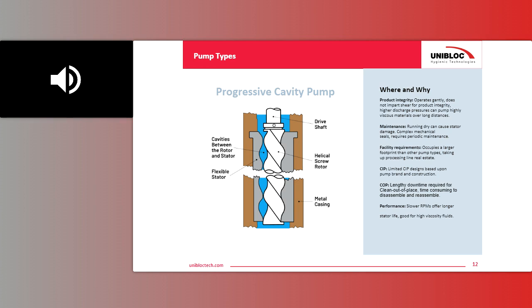They are also considered one of your higher discharge pressure pumps. So you're pumping viscous liquids. That's why you're choosing a PD pump, because its pressure capabilities are higher than the other technologies. You can pump more viscous liquids at longer distances with these type of pumps. So that's the other big benefit of a progressive cavity pump, its high pressure capabilities.